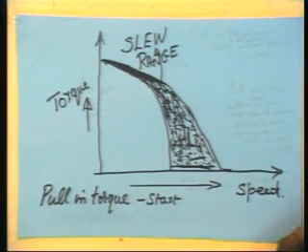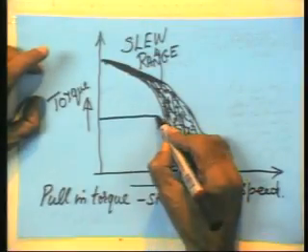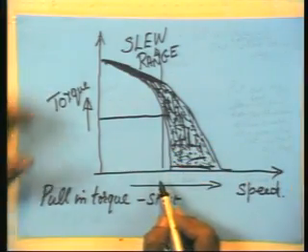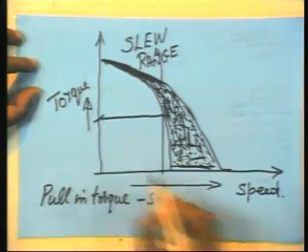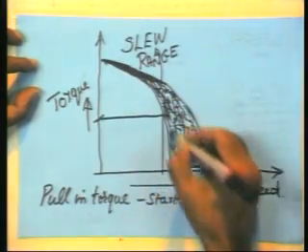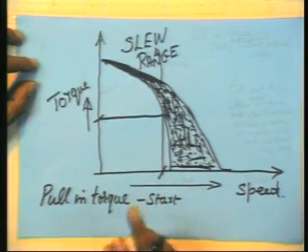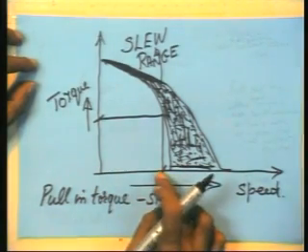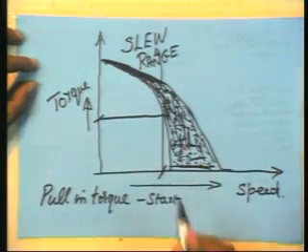For starting the motor, supposing you have a motor and a load, and you have a specific torque here. I have the torque, this is one point, I draw a horizontal line and come up to this. This is the maximum speed within which you can safely accelerate and decelerate. This is the pull-in torque. Given a torque load, this is the maximum speed.